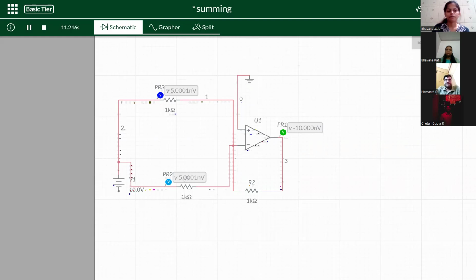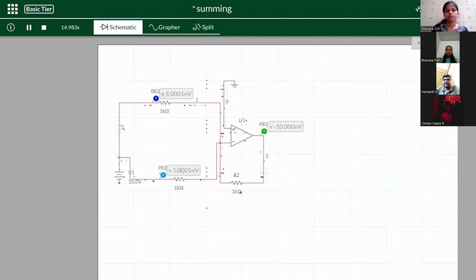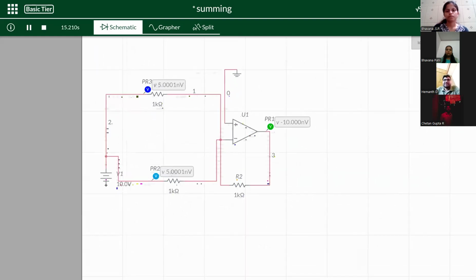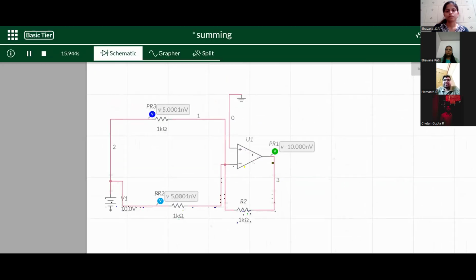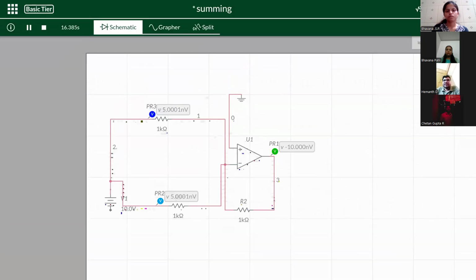I am going to state the problem statement of the differential amplifier. In practical electronic systems, signals of interest are often contaminated by unwanted noise or interference that appears identically on both lines, common mode noise. When amplifying small signals, it becomes crucial to reject this noise and accurately amplify only the difference input signals. The problem addressed by this experiment is to design, simulate, and analyze a differential amplifier that demonstrates high common mode rejection and outputs only the differential component, thereby improving the robustness and precision of analog measurements.